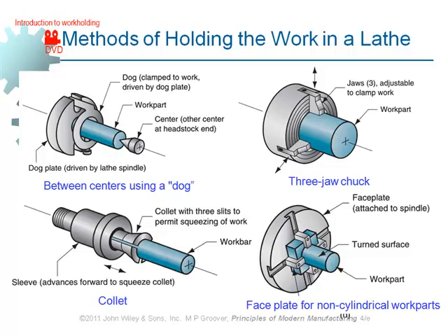The geometry of the part which is being machined on these two is different. On the one which is using 3-jaw chuck, the part is clamped from outside diameter, meaning that what you machine will be machined related to the external diameter. The one on the left, the part is clamped from the center holes. So anything which is being machined will be machined relative to the center holes, not to the external surface.